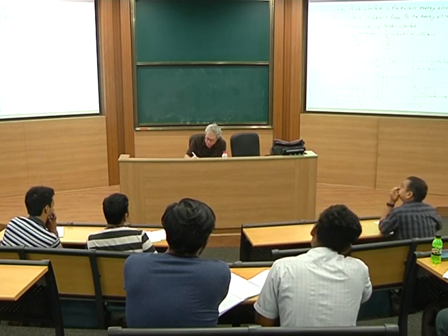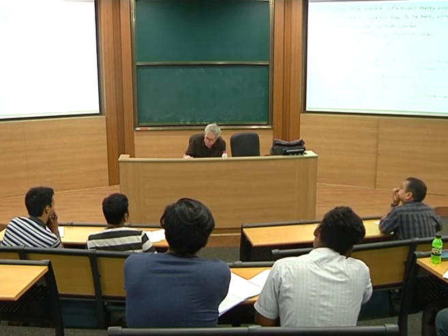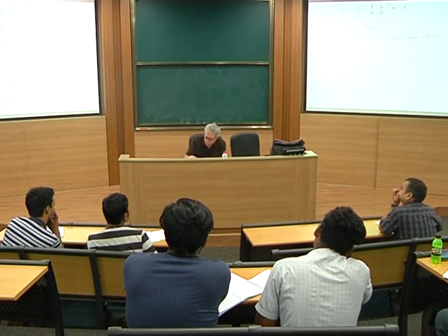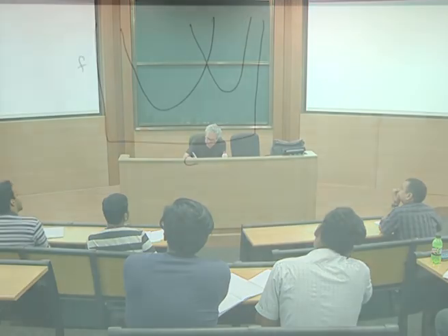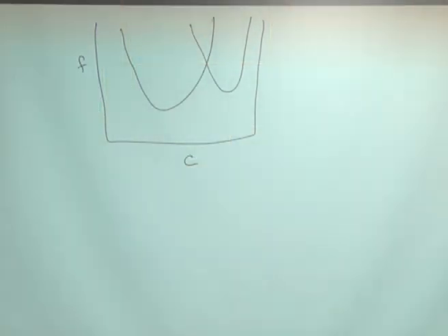is that if you look at a CALPHAD free energy function, or more general free energy functions. Remember, the assumption of the phase diagram is that they had the same structure, and that's a pretty limited set of phase diagrams, really, and they mostly look like this, where you have FCC, BCC, or solid liquid, or something like this, where you have two phases, alpha and beta now with different crystal structures.